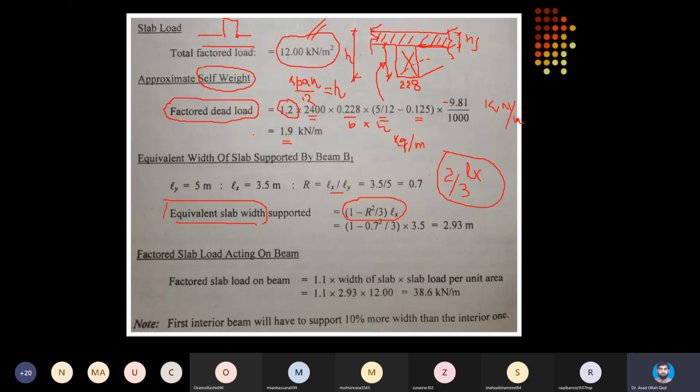But later on, if your depth comes out to be more than this, then you need to check whether this underestimation resulted in a serious drop in capacity, or whether you are still safe by rounding up the loads during the design. Such estimations are normally done on the safer side because later on you need not revise your calculations.